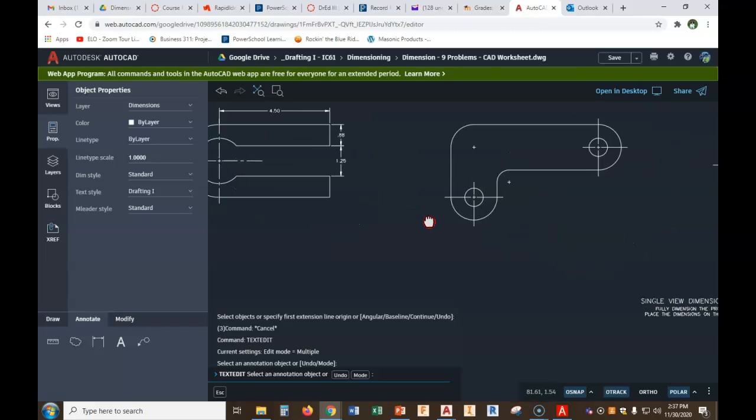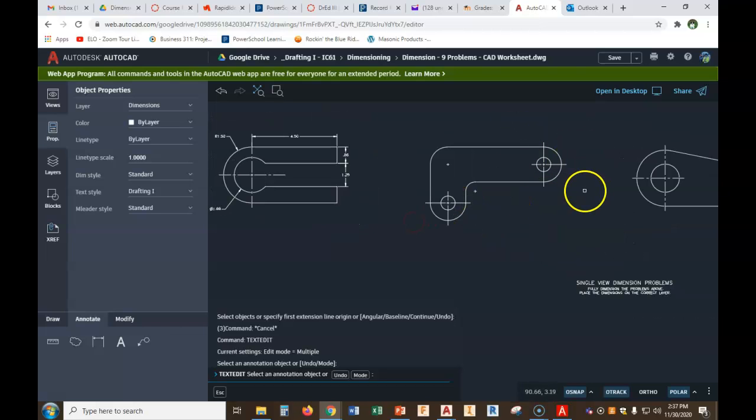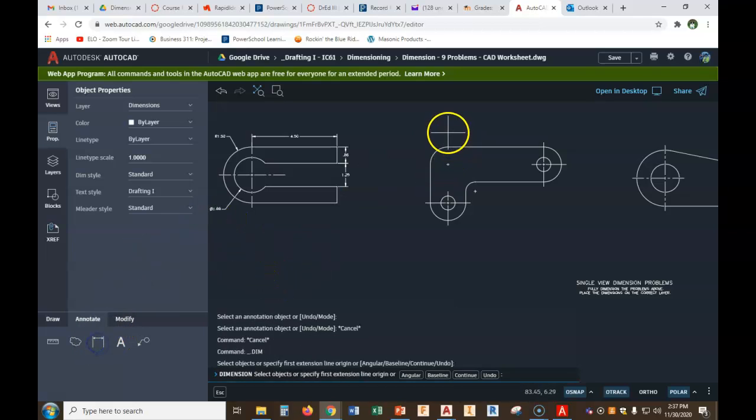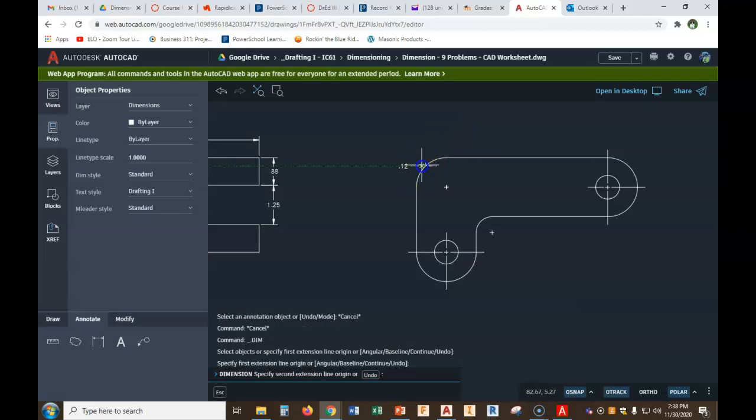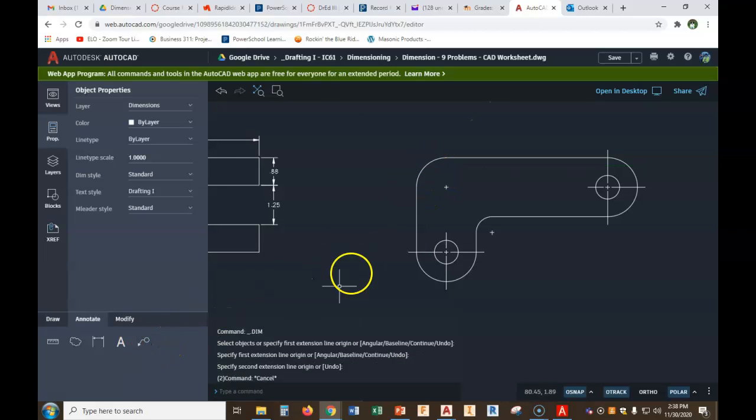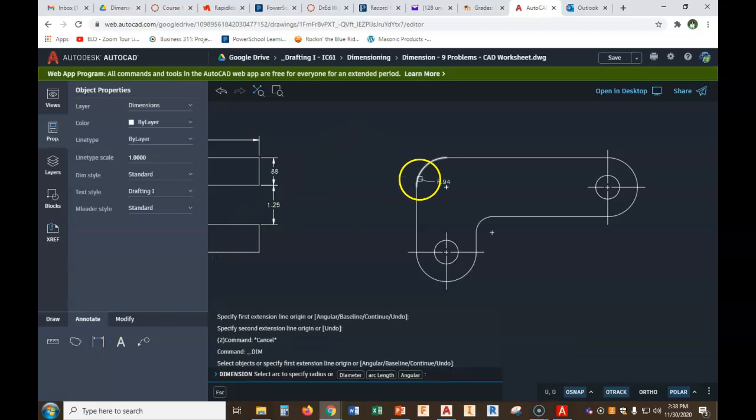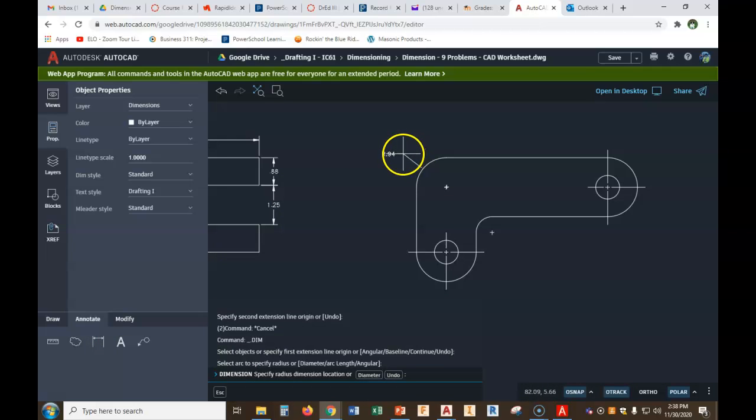That's it. All right? Now how about this one? Fully rounded end. That's just a rounded corner. Okay, so let's get started. Let's go dimension, zoom in, click on that, drag up. Uh-oh, look what it's wanting to do, because I didn't give it a chance. When I grabbed the midpoint of that arc, it messed it up. Come down here and sort of touch down here. Now click, and now you can drag it wherever you want it.